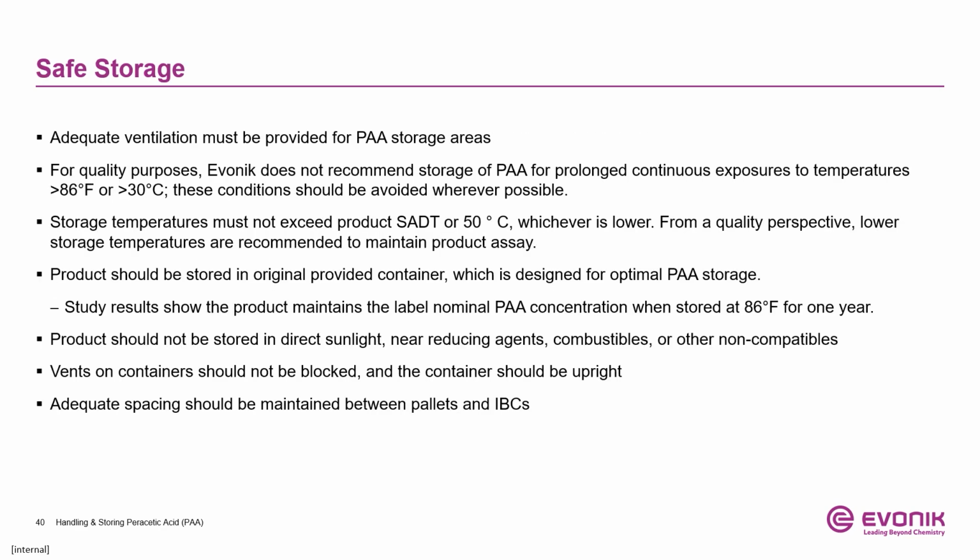Adequate ventilation must be provided for PAA storage areas. For quality purposes, Evonik does not recommend storage of PAA for prolonged continuous exposures to temperatures greater than 86 degrees Fahrenheit or 30 degrees centigrade, as the product will lose assay more rapidly. These conditions should be avoided whenever possible. In addition, make sure that it is not stored in direct sunlight, near reducing agents, combustibles, or other non-compatibles.